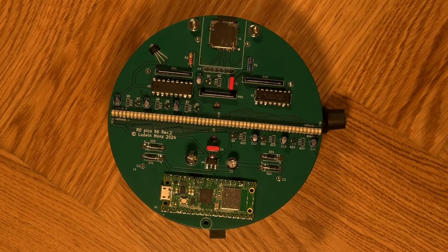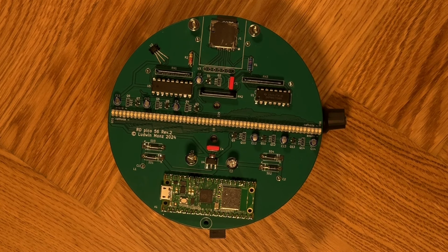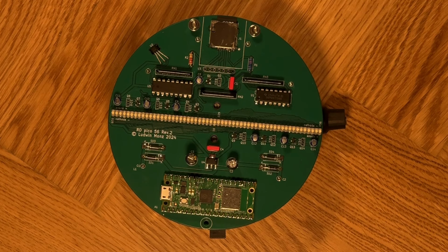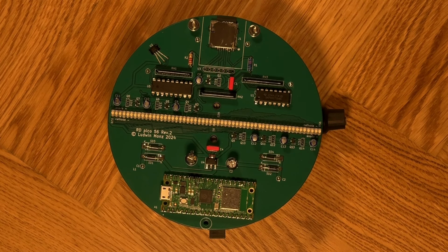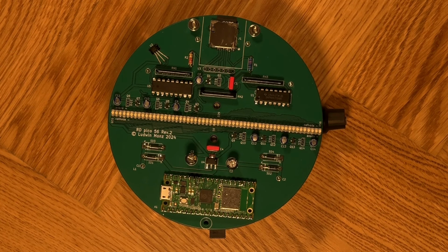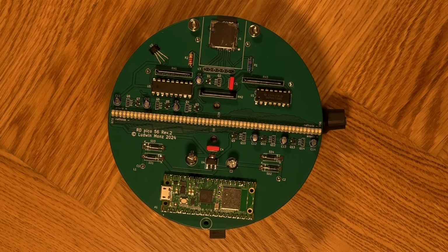The microcontroller is located at the bottom of the PCB. The alternating field of the wireless power supply is weakest at this point, which avoids interference with the Wi-Fi function of the microcontroller. The rectification and voltage stabilization of the display is located above the microcontroller.